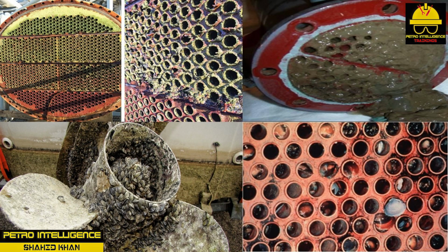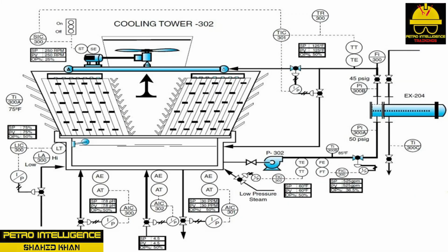Unfortunately, chlorine is an extremely hazardous material and must be handled with caution. Bromine is a little safer to handle and use. CTW302 utilizes a special blend of biocides to keep the cooling tower operating smoothly. Other chemical inhibitors are added to this blend and need to be thoroughly mixed with basin water.